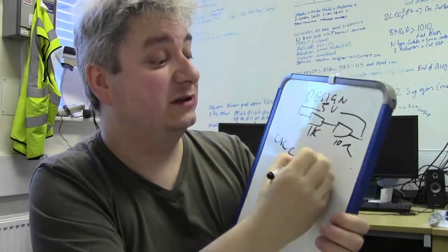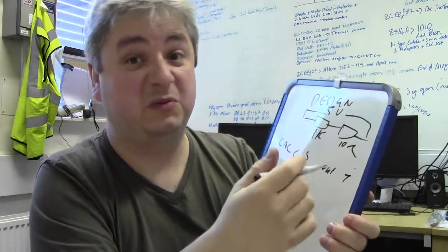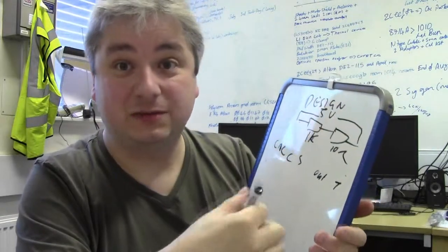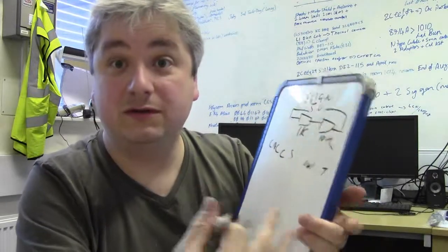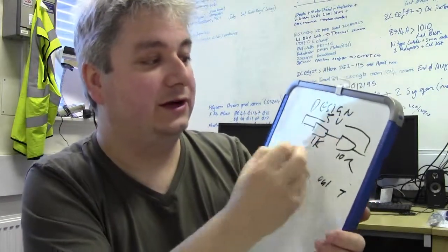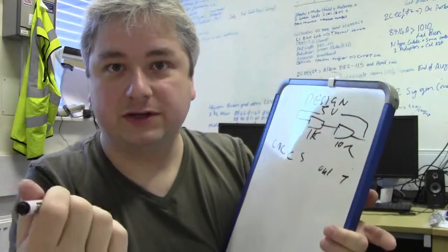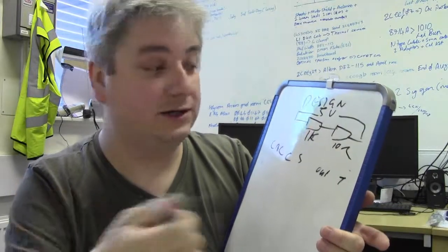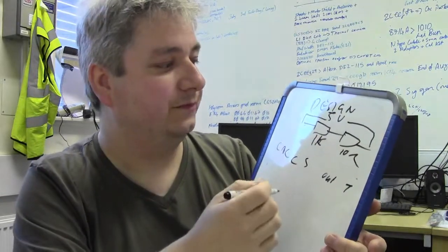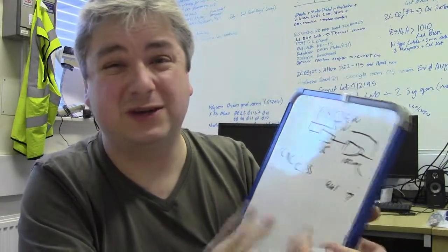So, calculations: you have to calculate the output for tolerance. If my resistor is 5% greater than what it should be, work it out. If it is 5% less than what it should be, work it out. What sort of ballpark figure are you actually going to design for? Same with power. Find out how much power is being dropped across your resistors. Very important: if you buy a resistor which has a lower power rating than what is actually going to be developed across it, you could end up setting fire to your resistors and burning out your circuits. You can just switch it on and you're just wasting some money.